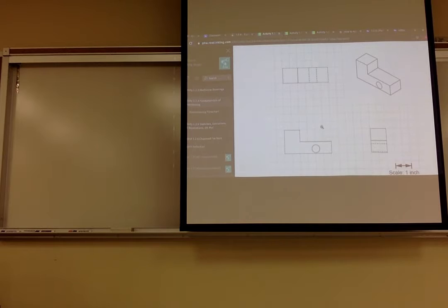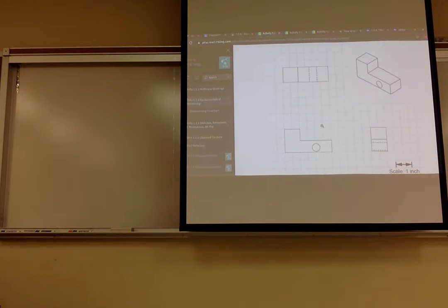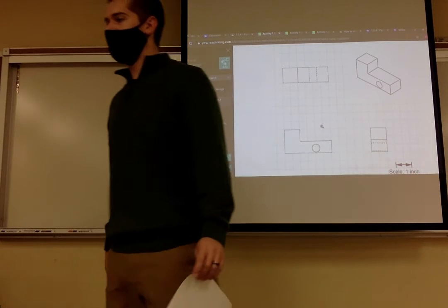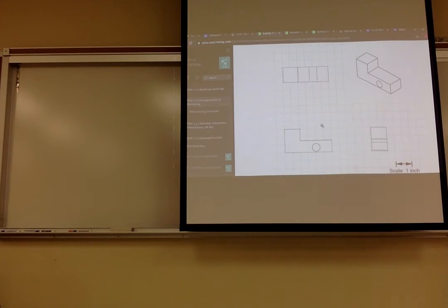No. You would want the overall length, and then you would need to dimension this length, and then you're good. Because I would have this measurement and this measurement, because I do the total minus this, and I can know that. So you would just write overall, this one, and then add 1 more, and then you're good for that side. It's fully dimensioned.